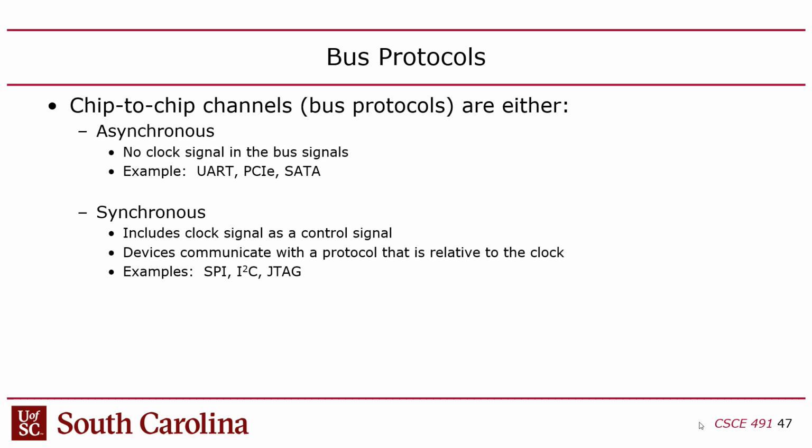So what may end up happening is that one side of the connection may be changing the data when the other side is reading it, right? That sort of system only works for low-speed interfaces like UART. And even then, it's going to fail sometimes, which is why you have to have some kind of error detection mechanism if you do that, which UART has, called parity.